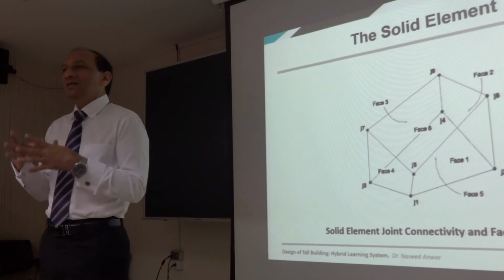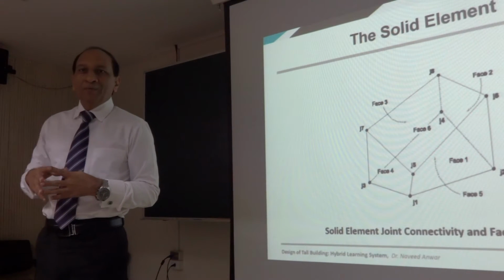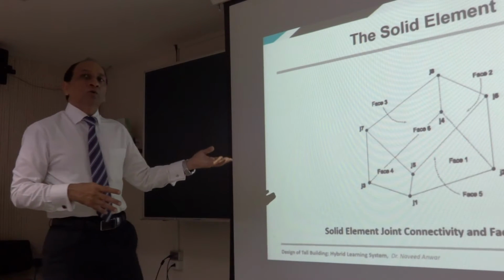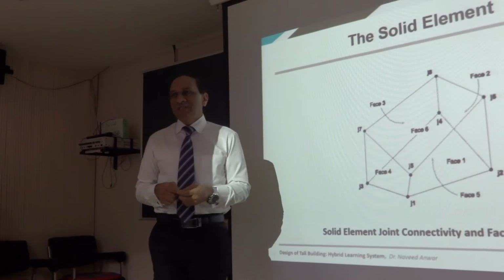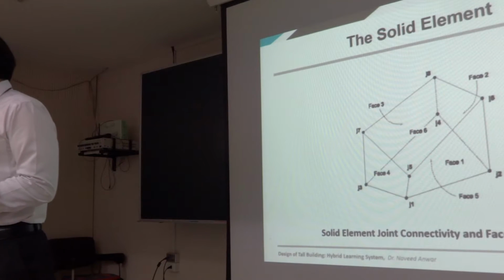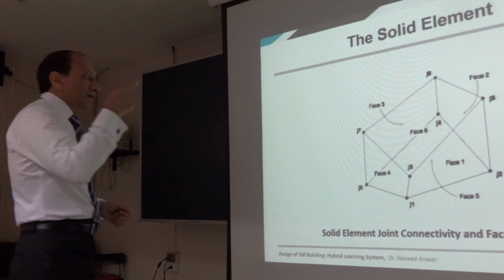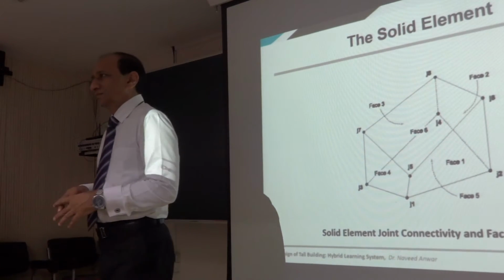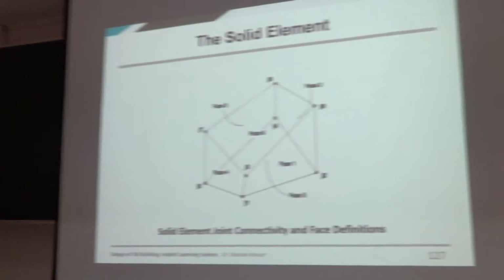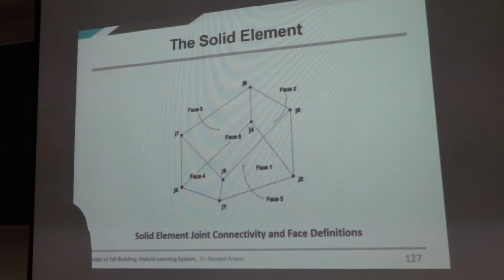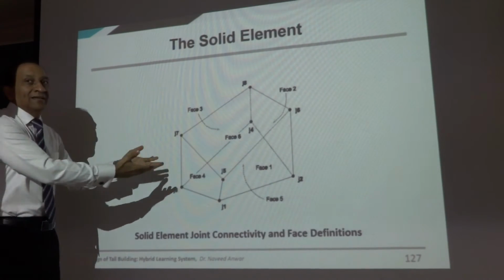Line element needs 6 geometric properties, 1 material properties in general, or 7 properties plus 1. Plate, shell or 2D elements need 1 geometric properties, which is thickness, plus 2 material properties, which is the E and mu. Alright? How many geometric properties will a solid element need? Zero. You do not need any geometric properties for solid element because you are physically modeling it.